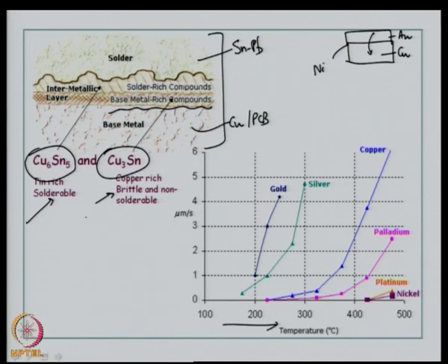That is why you have to make sure that the soldering process is done on a clean copper surface, and if you try to repeatedly do desoldering and soldering on the same surface, you will not get a wet joint because of the different intermetallic layer that is formed, which is not amenable to the soldering process.